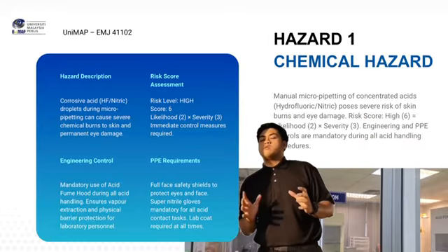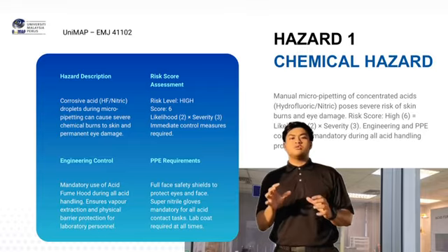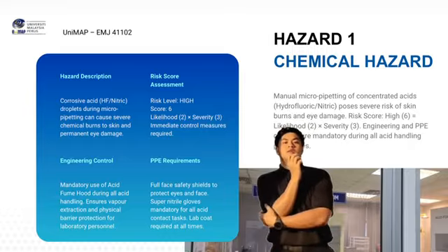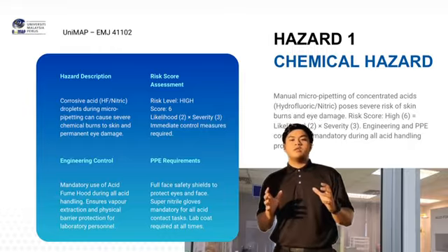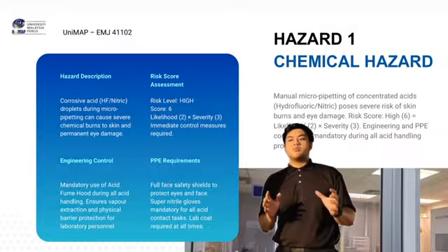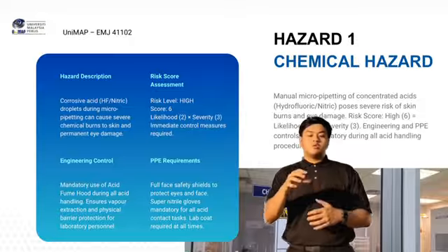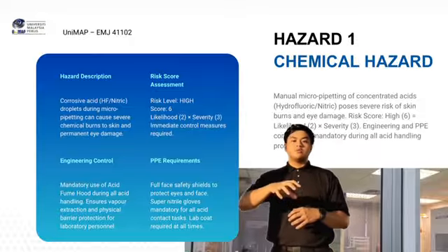For the control, it is mandatory to have acid fume hoods to extract the dangerous fumes when handling chemicals in the laboratory. It is very mandatory. In order to handle any chemicals in a laboratory, you need acid fume hoods with an exhaust fan to suck the fumes out.